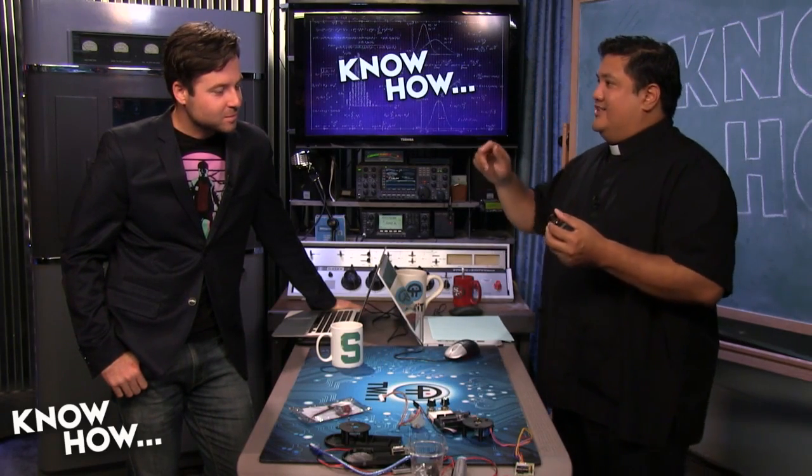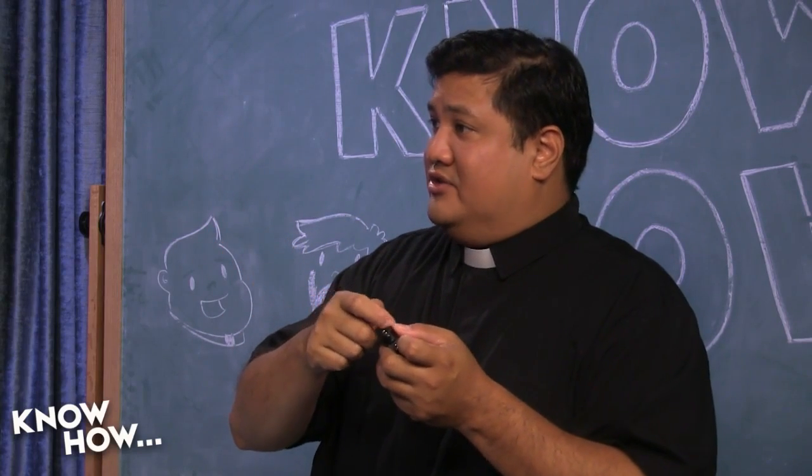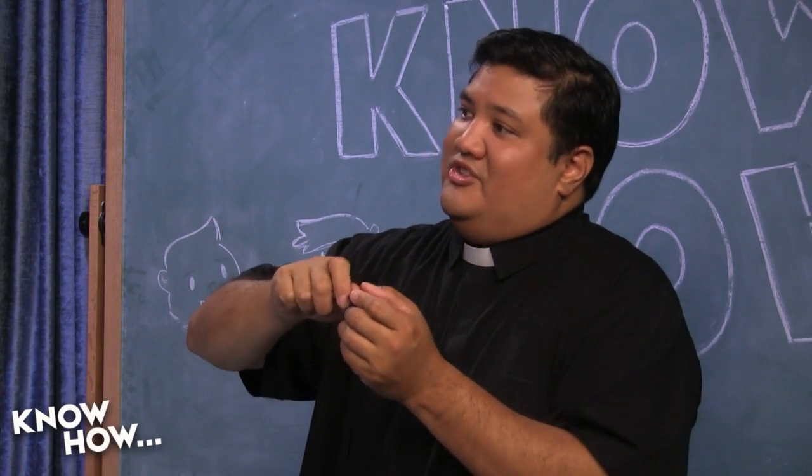Okay. So, that's why I decided I wanted a thicker part. I didn't like that little skinny part because I didn't like the idea of clamping down. In fact, the original design didn't have an insert for the nut. So you were just using the resistance of the plastic. Yeah, and that's not a good idea. Yeah, well, that's a really good way because it'll just strip. The bolt will pull out, and it'll probably pull out at the worst possible moment when you're actually supporting weight.